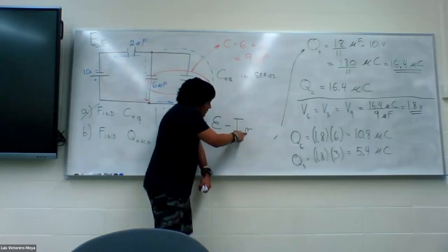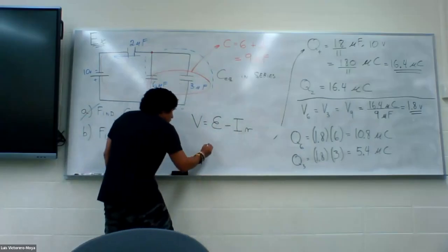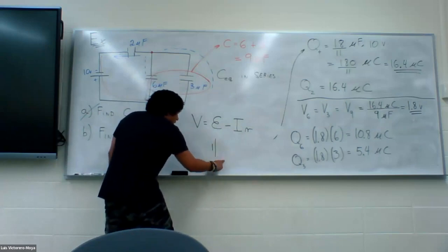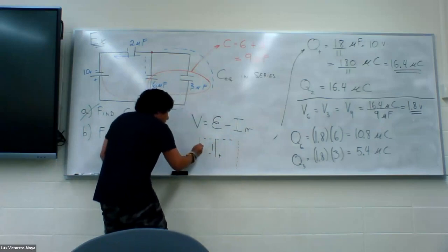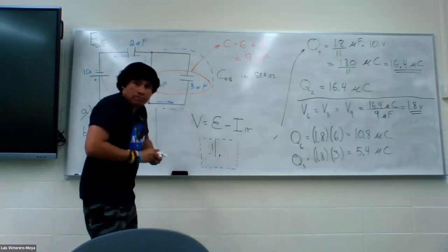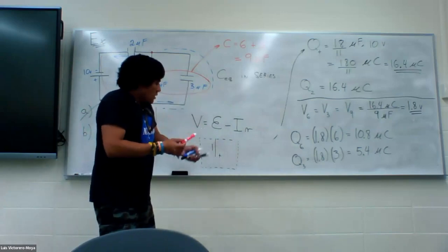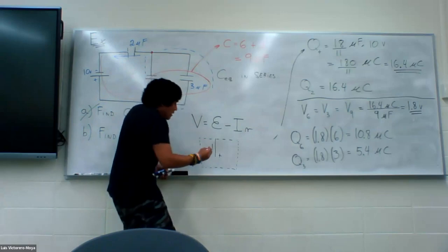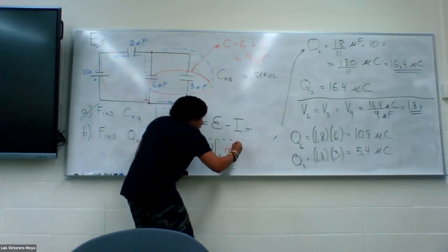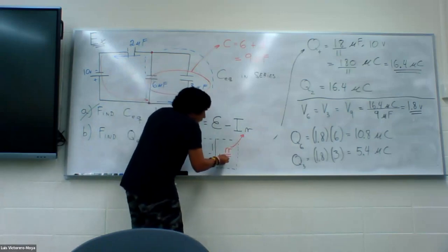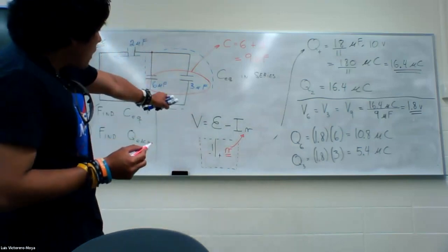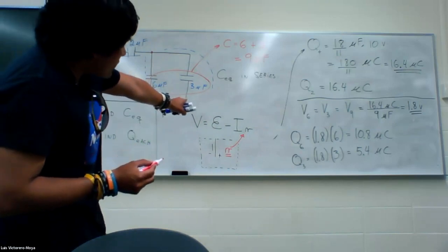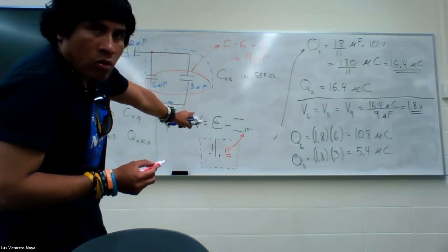This r, if I were to draw a battery, in real life, a battery is not like this, right? It's a device. I mean, you have seen power supplies in the lab. Those big green thingies. A power supply or a battery has an internal resistance r inside. The internal resistance is the reason why the voltage is different than the theoretical value, or the EMF.